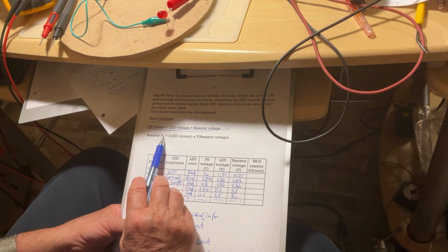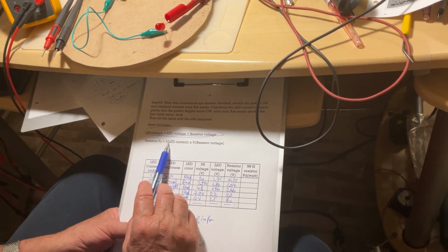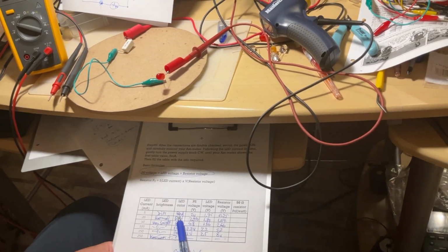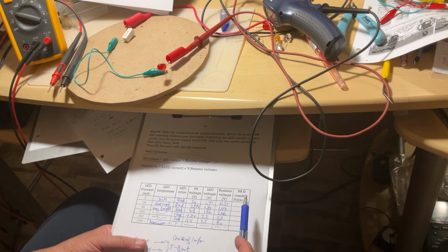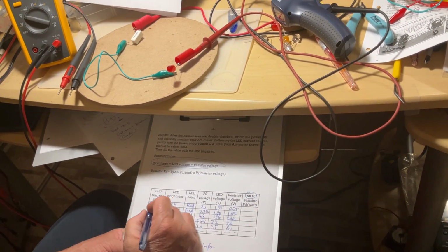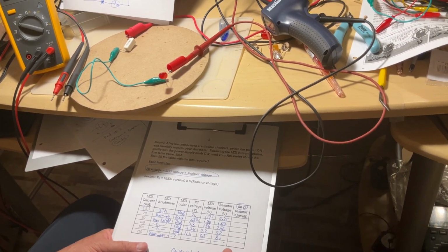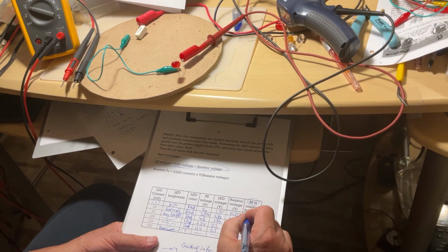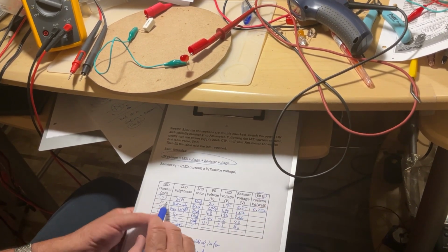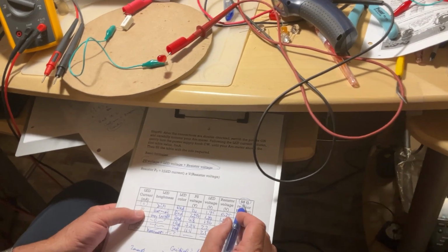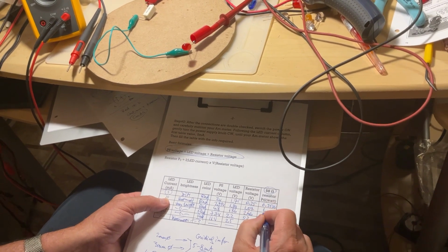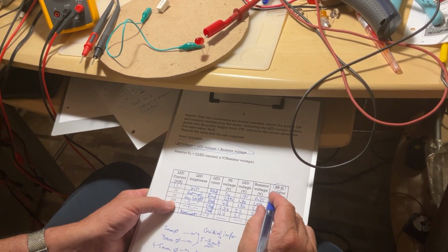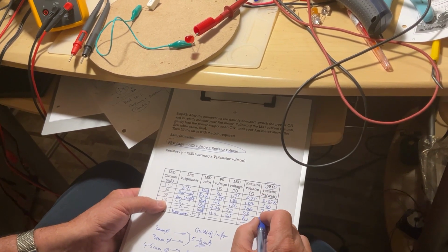And now the resistor power dissipation, which is from the current passing through the LED. We have a series circuit here. So the same current passing through the LED is going to pass through the resistor. So if we just multiply the 50 ohm resistor by the milliamps, we have the power in milliwatts. So no big deal to convert it to watts if we need to. So 50 times 5 is 250 milliwatts, so 0.25 watt. Here, 20 milliamps times the same resistor 50 is 1 watt. 50 is 2.5 watt. 100 times 50 is exactly 5,000, which is 5 watt.